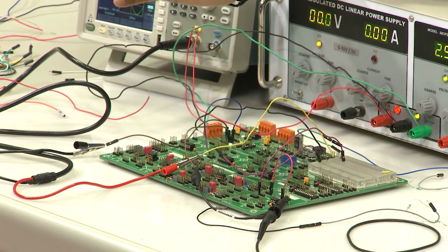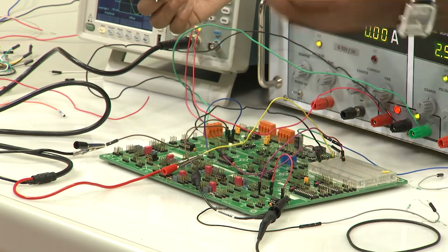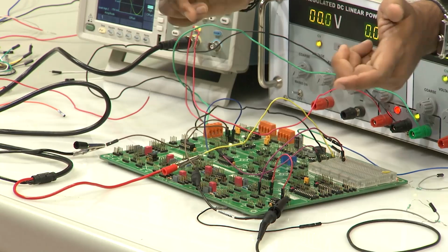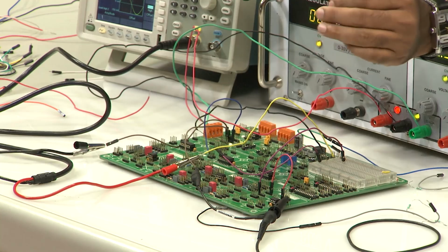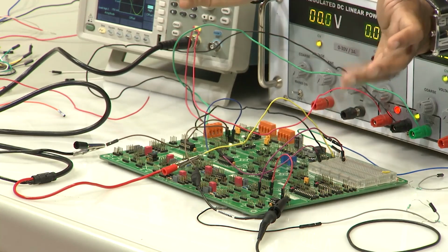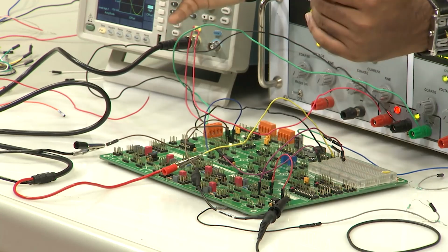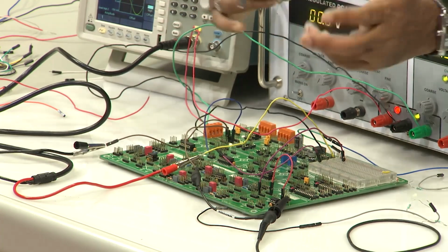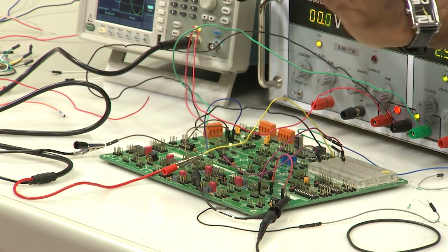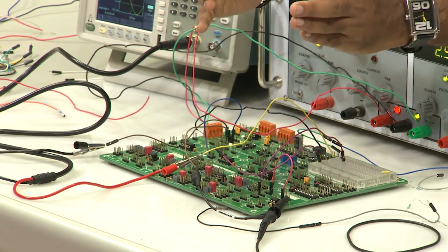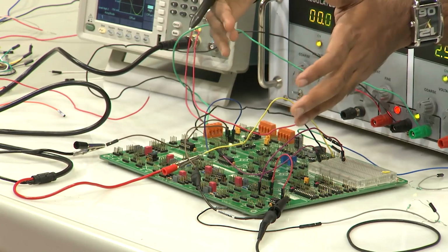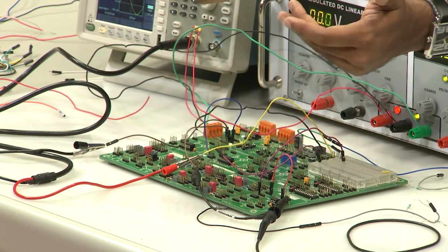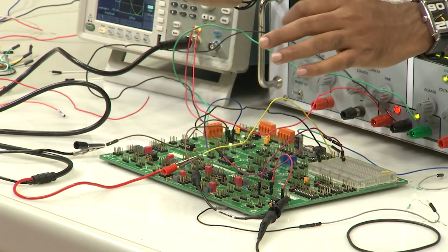It is a very simple circuit, but it has a lot of applications. It can be called the unity follower, the buffer amplifier, or the voltage follower. It acts as a good impedance stage, and it also helps you to invert your output. Let us say you use the inverting amplifier stage to get the output, and you want an output that has the same phase relationship with respect to your input. So, you add another unity follower after that inverting amplifier block, and you get the output in phase with the input. If you just use the inverting amplifier, your output will be out of phase because the gain is -1, correct. So, that is the overall idea.